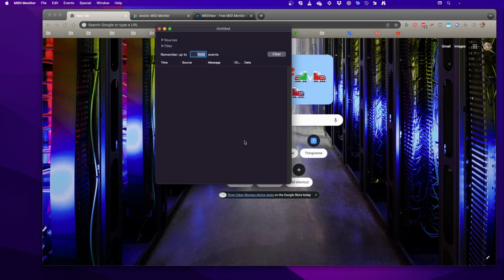And when I push a button, I'm actually recording this in OBS right now, so when I push the button, it's going to be for this particular source that I have selected that's sharing this desktop, so it doesn't change. And there it comes in. Now notice I got 2, so the debounce, you can tell, needs some work on that. Plan is to have a hardware debounce mod in the future. If you modified that timeout value, you could avoid that.